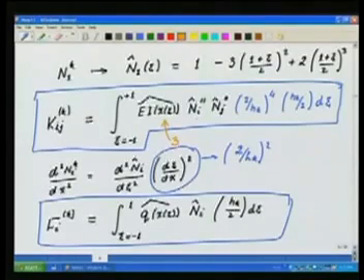The second derivative of Ni, since Ni was cubic, second derivative is linear, second derivative of Nj is linear. So, here the order of the integrand is 5, if I have taken the beam to be a tapered beam. If it is a beam of constant cross section, that is h and b are both constant, then this part will become 0. So, this integrand is essentially of order 2.